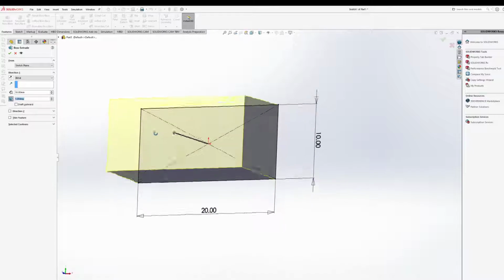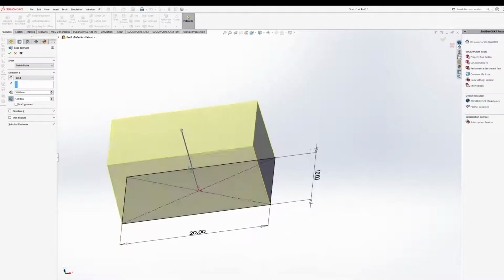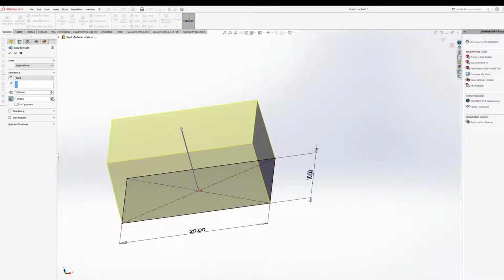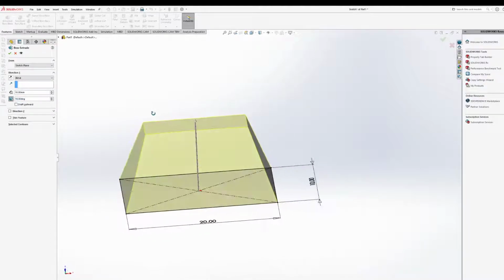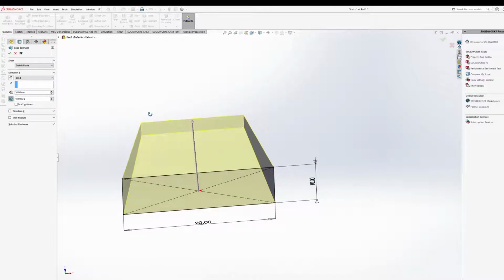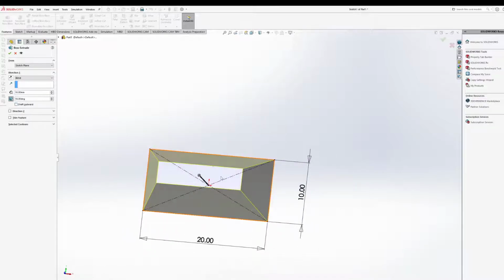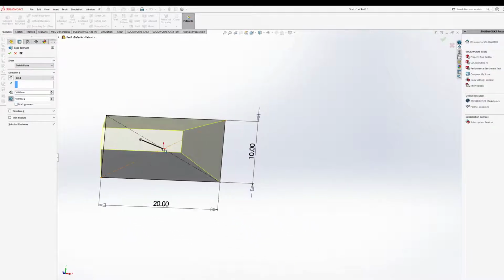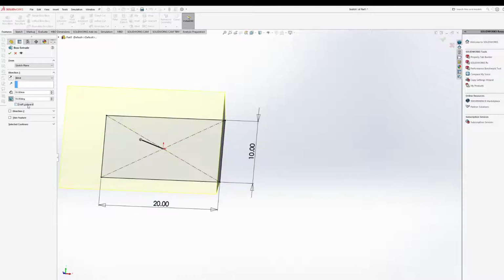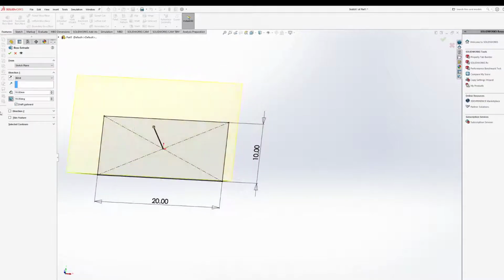And then, if we're going through some of these features, draft is pretty cool. I believe it defaults to inward. So this is a good way of saying, hey, maybe I want to create something that's more of a trapezoidal prism or something of the sort. Just any shape that requires some additional angle out of our extrusion. We can do that as well just by saying, hey, let's draft it. Or maybe it wants to be outward instead, anything like that.